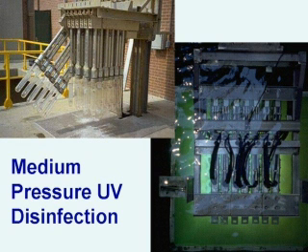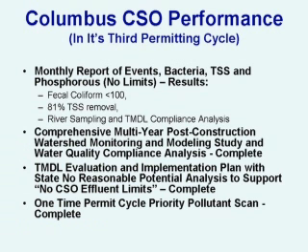This photograph shows the sodium hypochlorite system. There are tanks within a containment area, in case they break, and there are metering pumps. In Columbus, different from Atlanta, they are metering pumps that have variable speed drives on both the speed and stroke. We have a control algorithm that I'll talk about later on how the chemicals are fed in, because it changes throughout a CSO event. But they essentially pump the chlorine into the vortex vessel influent, and then the sodium bisulfite, which also runs on an algorithm, is pumped in at the effluent of the vortex to take out any residual chlorine that was not used up. I ought to note that in Columbus we're disinfecting the flow for the chemical side of the flow before any solids are removed.